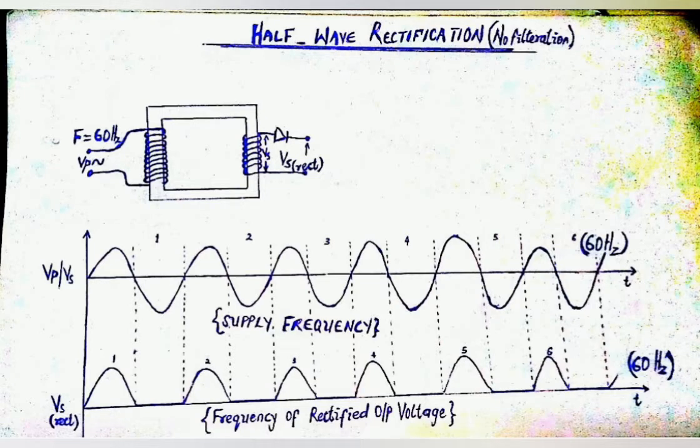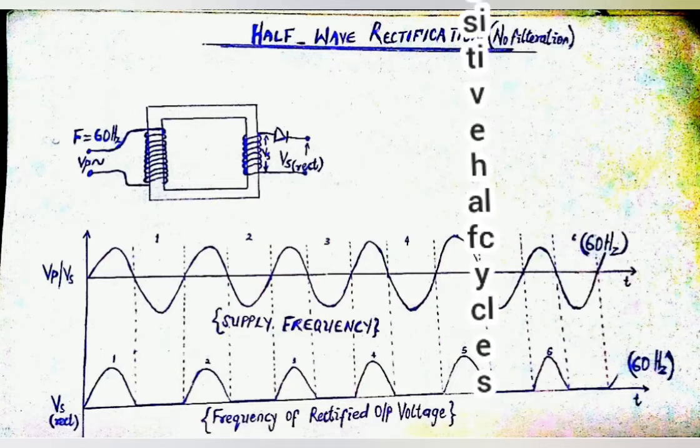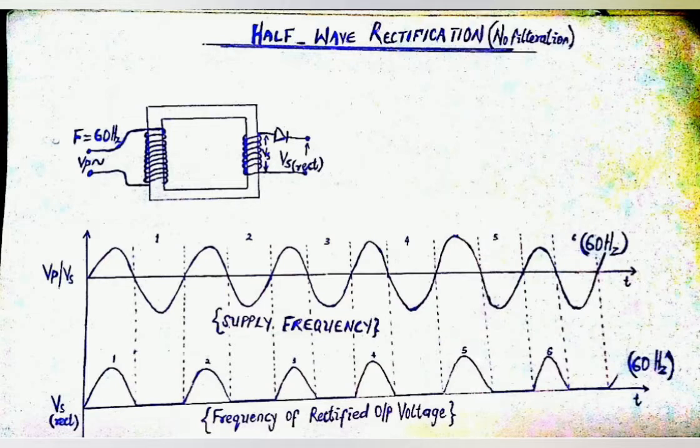Here, the sinusoidal waveform of the AC input voltage is modified after current flows past the rectifier components, which is the diode, as seen on oscilloscopes. In half-wave rectification, only the positive half-cycle of the sine wave flows through the rectifying part of the circuit, while the negative half-cycle is attenuated.